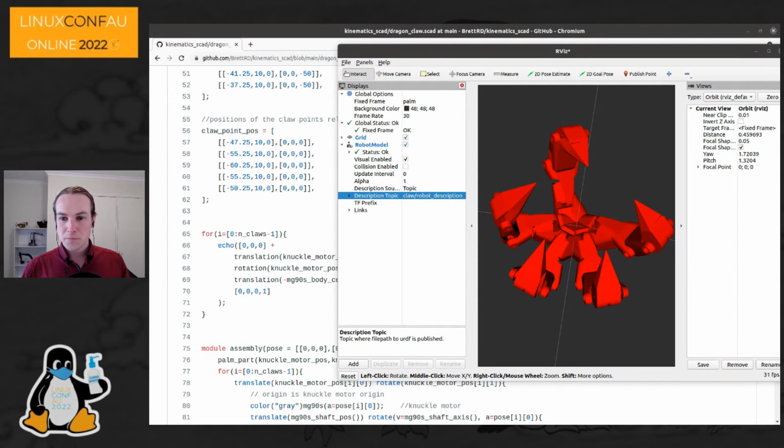The connection between the computer and the robot is, you can take your pick. At the moment, I'm using the MicroROS agent over wireless, with UDP transport over Wi-Fi. That thing is just battery powered off a drill battery. You can also use serial or CAN bus. You can make any transport over anything, as long as you implement it as an actual ROS transport.